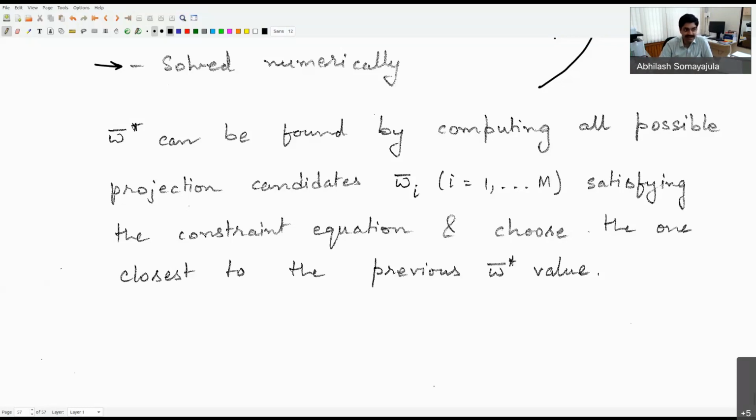Then we looked at the idea of curved paths, how to generate curved trajectories given a set of waypoints, and how to plan a path through them. And then we figured out how to follow that path, which is what we discussed today, using a proportional LOS guidance scheme. Okay. So these are the different methods which we have looked at, particularly with respect to the guidance technologies.